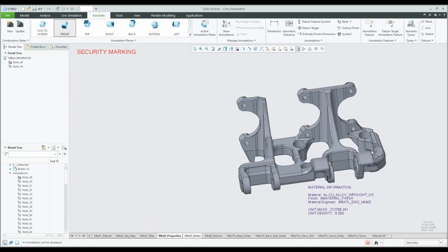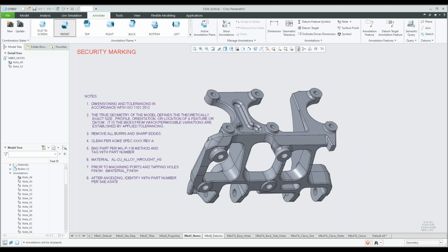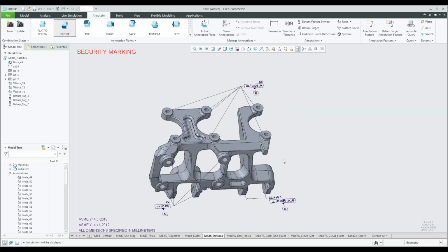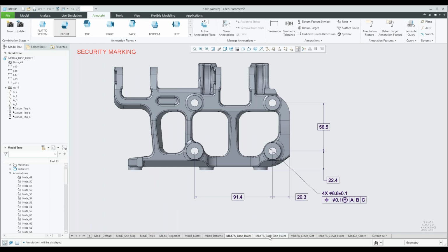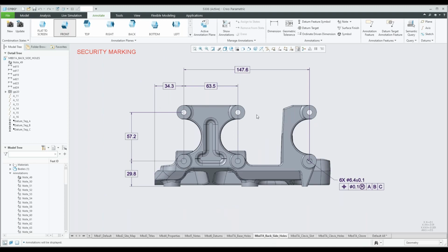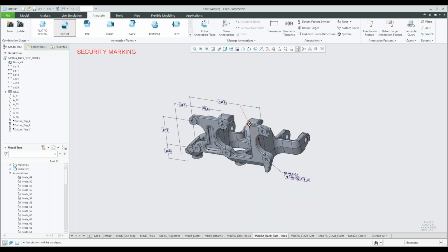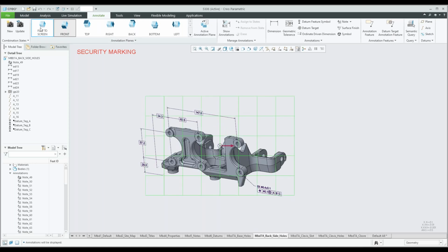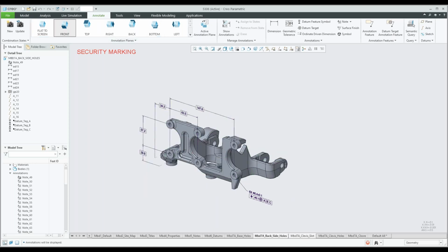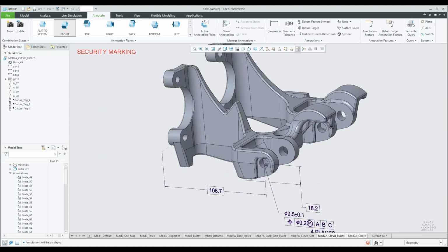And then if we go to another sheet, just more information regarding the manufacturing side of the part. Then we've added some datums, with the geometrical tolerance. So those are the type of things that you can add. Then some hole positions. The other hole positions. And you will notice these views, they will rotate with the component. So it's not set to flat to the screen. There's a certain orientation. More information. And then we also have a cross section in that one.